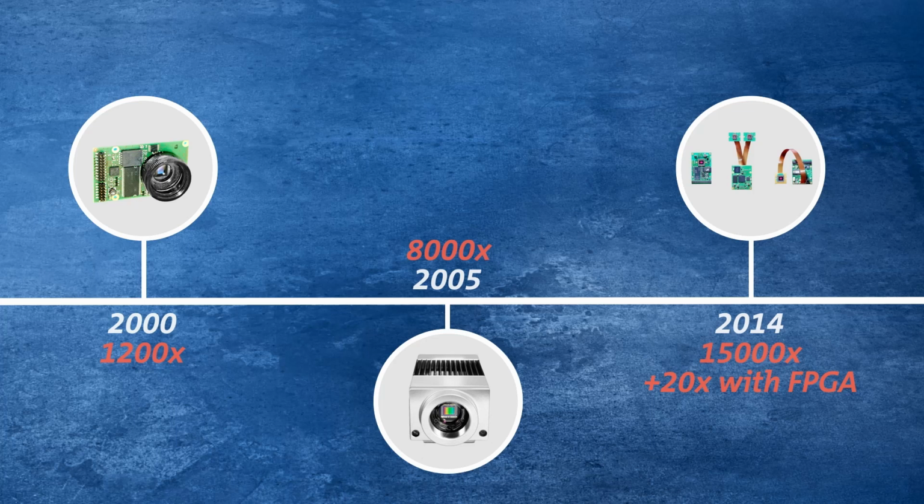Then it took some time to also take advantage of the FPGA that is inside the processing unit. As I said, it's a system on chip based on 2 processing units, a dual core ARM CPU and an FPGA. Now the FPGA, if you take this into account, can speed up applications by a factor of up to 20. So this is a huge jump without changing anything in the size, because it's still the same hardware. You can just get more out of the performance of the hardware by implementing FPGA blocks into the final product to have a real increase in computational power.